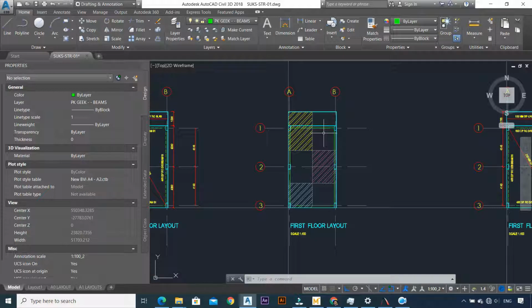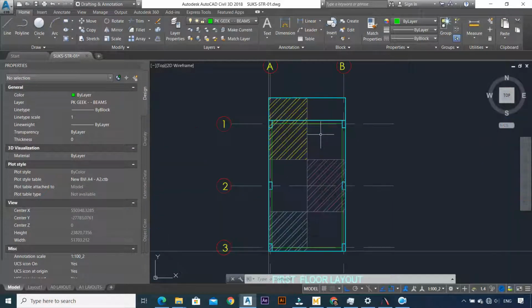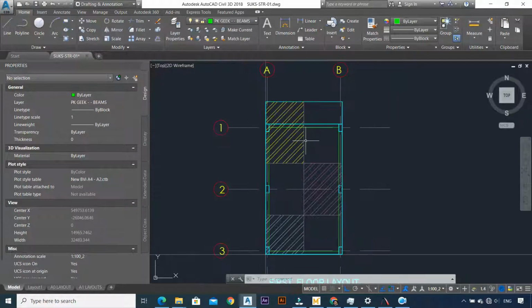What you do is create a line between the two centers of your supports, and then you bisect at the center of that line that you've just created. And wherever the bisectors of the center lines, or these lines that span from the center of one support to the other support, meet, that is where you are able to get your tributary areas.